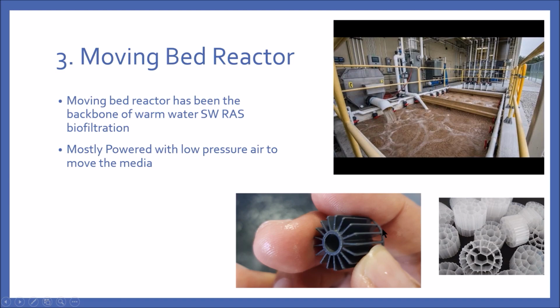The third is what we call the moving bed reactor. The moving bed reactor has been the backbone of warm water, salt water RAS biofiltration. This media is not made up of sand or stones. They are made from plastics.